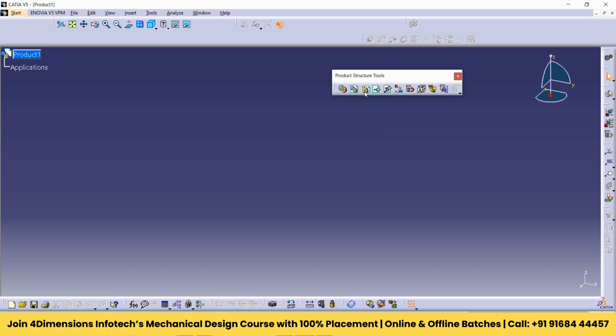Now to make a part in assembly, we need to click on this option, that is Part in the Product Structure Tools. So I'm going to click on this option. Then we need to click on the assembly title, that is this Product1. In the model tree, Part1 is going to appear here.